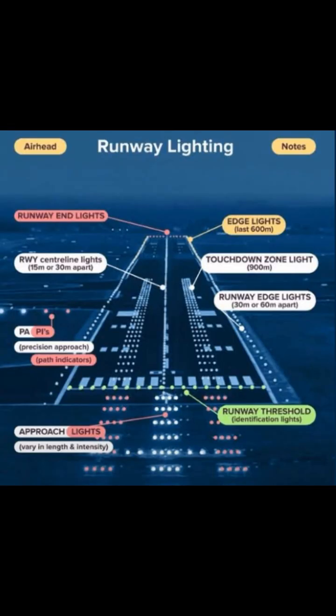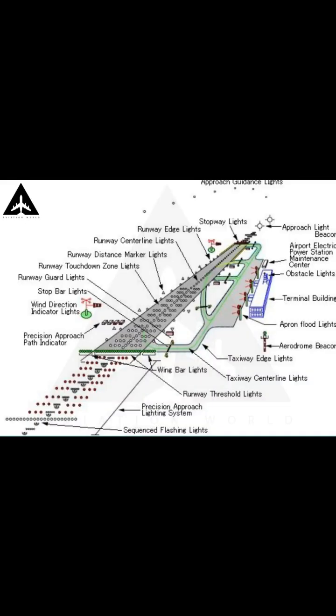Airfield lighting system. An airfield lighting system has many miles of circuit cable. The system has miles of cable originating from the source of power to the runway, plus the distance around the runway itself. The only practical way to light a runway and taxiway system is to use the series circuit principles. Figure 6-7 illustrates how large the system may be. The voltage losses caused by the resistance of the copper lines do not permit a practical application of a parallel circuit. The lighting consists of a series circuit with a transformer located at each individual light location.